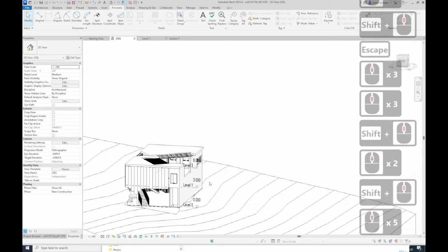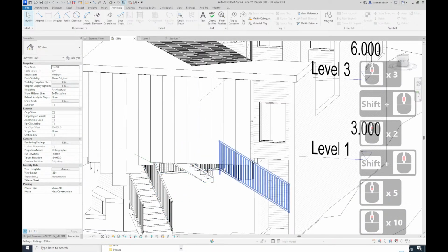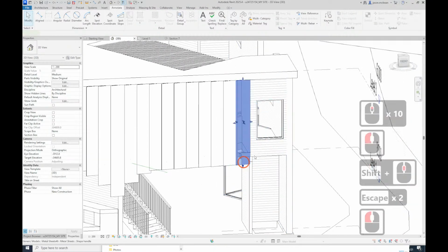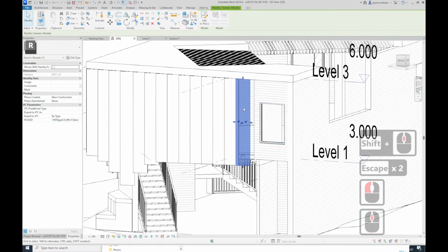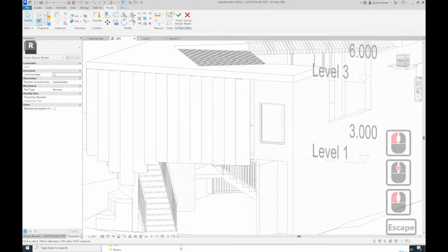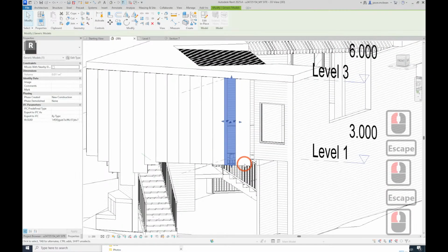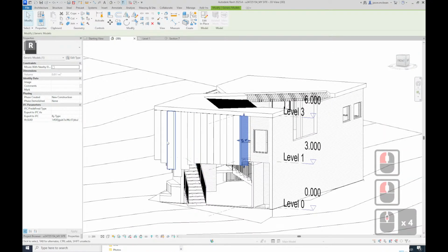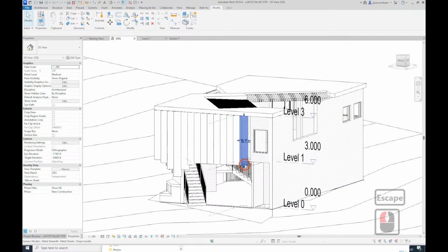Okay. Then I have a question for these. These are perforated. Do I draft the perforation, or what do I do? Is it like a mesh? Yeah. Okay, this is quite interesting. You've modeled these in place, I see. Edit in place. Just be careful. You want to add all of these to the same in place model. And there's a trick to do that, because now you're going to have hundreds of these little things, all in different heights.